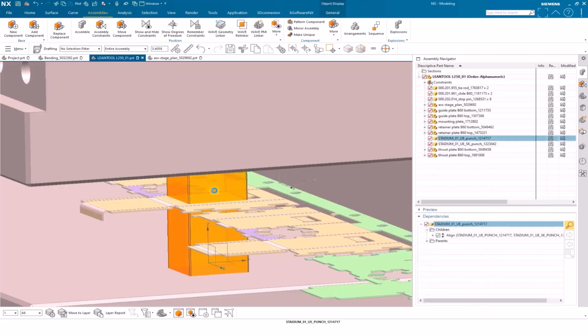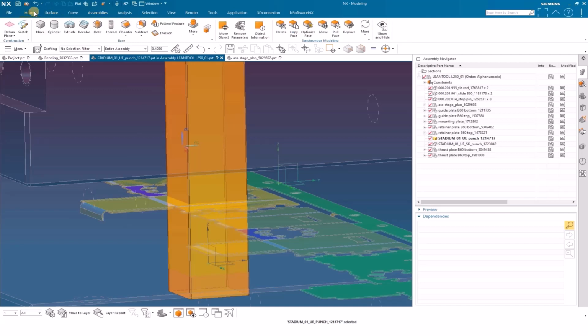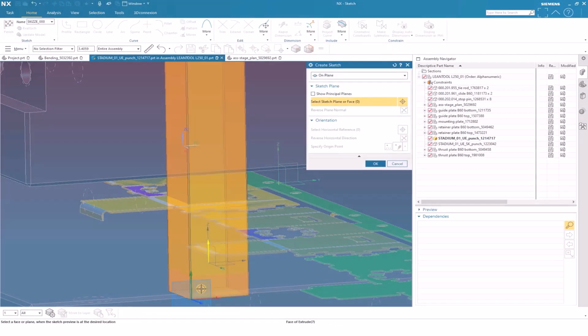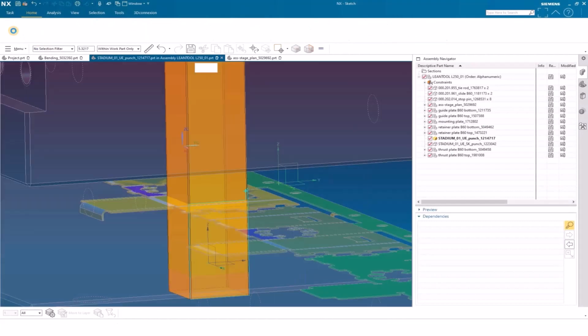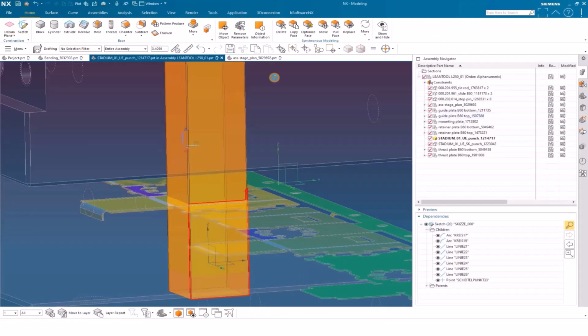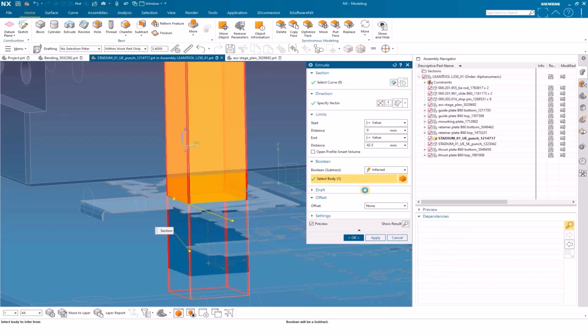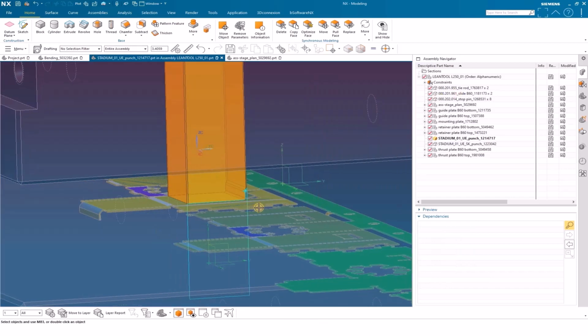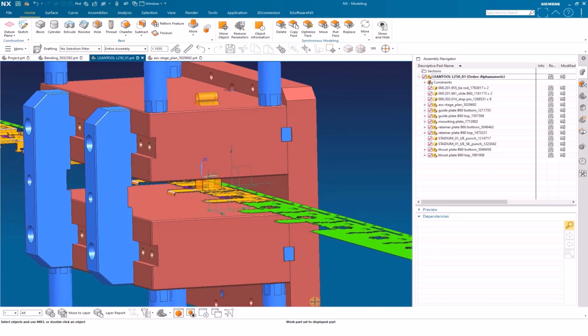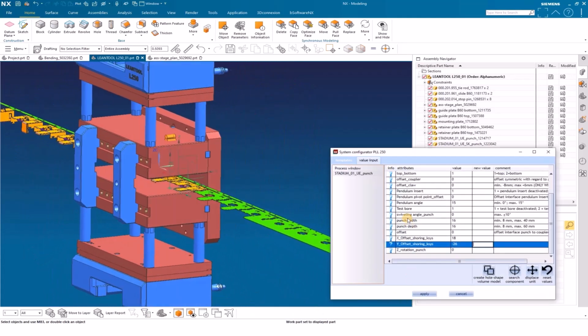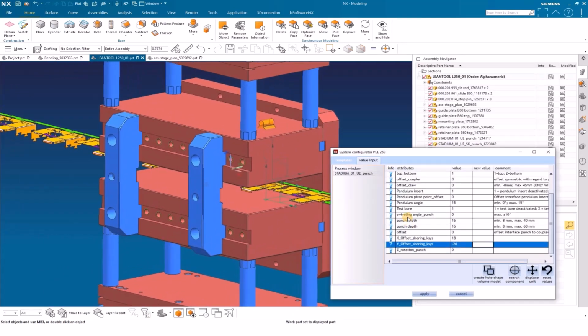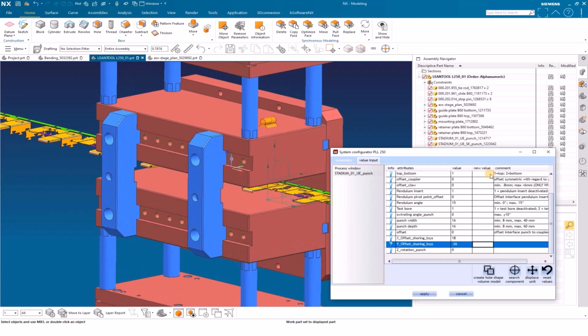For the stamp contour, the stamp is adjusted with standard functions. Here the contour is sketched and extruded. The direction can also be changed, depending on whether the punch should come from above or from below. The pendulum angle refers to the coupling. For the piston it is the swivel angle with limits ±10 degrees.